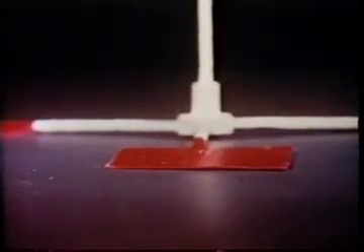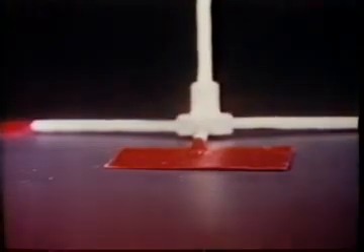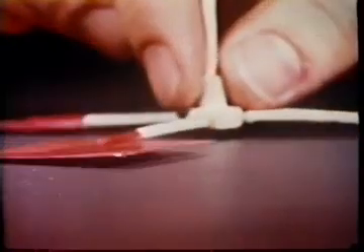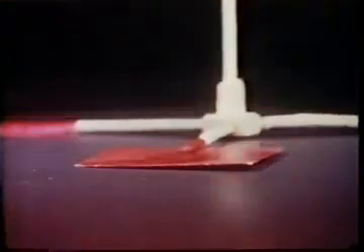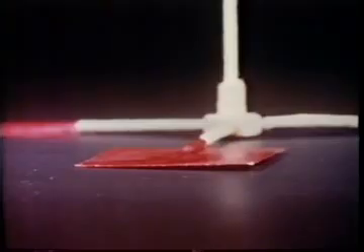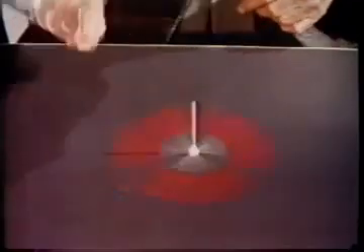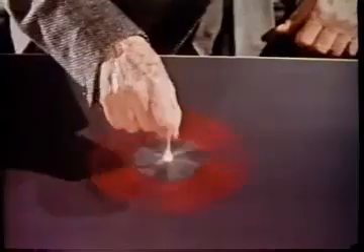Each of its blades is inclined slightly upwards. If they turn counterclockwise close to the tabletop, air is swept into the converging space and gives rise to this distribution of pressure under the blades. The pressure so produced by the counterclockwise motion supports it for some time. The apparent backward motion that you may see is a stroboscopic effect.